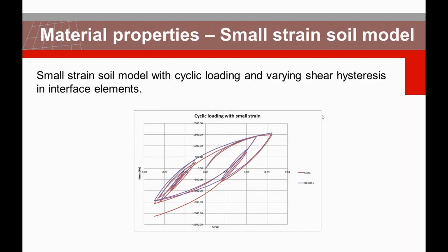As I mentioned, when you have a structure, between the foundation and soil there is a kind of connection, and when the model is subjected to an earthquake, this interface between the foundation and the soil is going to be ramped, close, open, and there will be some permanent deformation. And this way, using our new interface element, you can also capture that behavior in soil structure interaction.